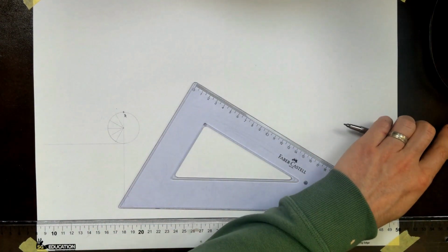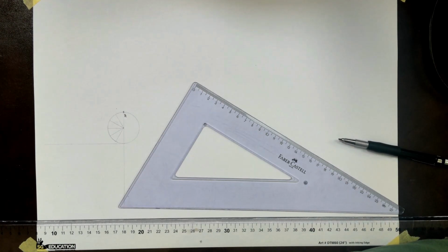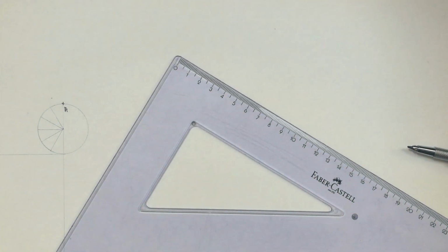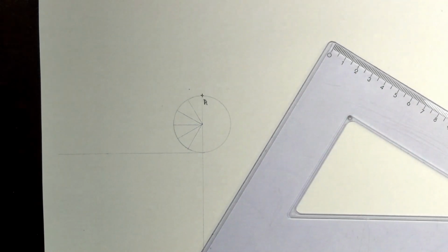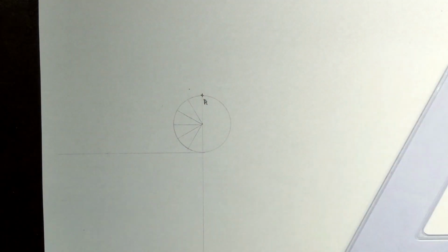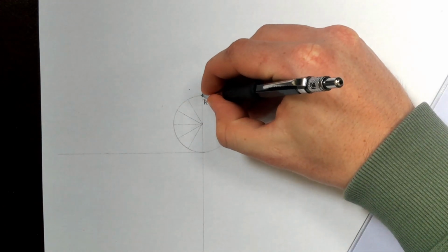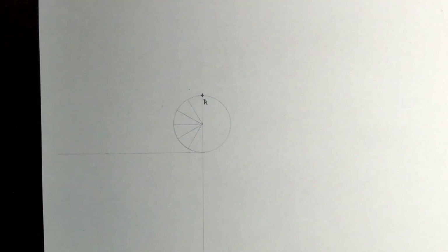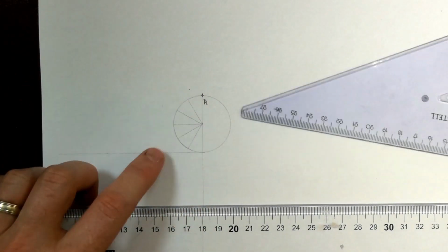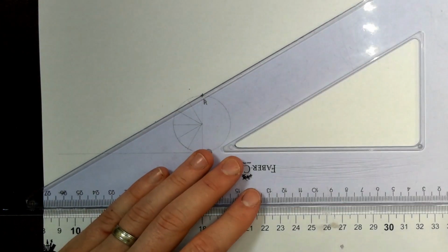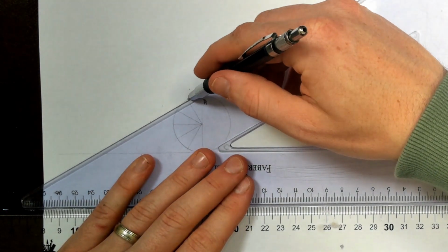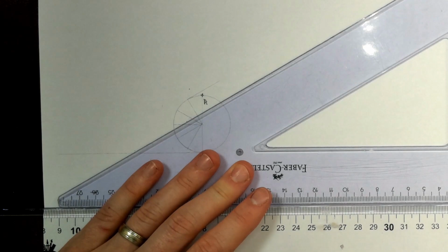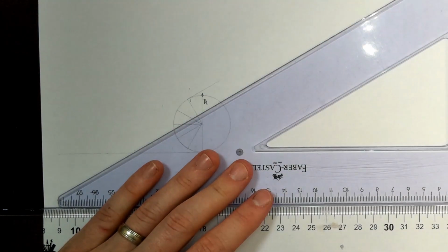So I've divided that side up. Now I'm going to zoom in a bit, because there's no point in being zoomed out that far when I'm working in here. My involute is starting here, so that's my first point. Now for my second point, I've divided this into 6. The 60-degree lines and the 30-degree lines are all done with the 60-degree set square. Where this hits here, I need to draw a line perpendicular to it, like so. That's created a 90-degree angle in there.